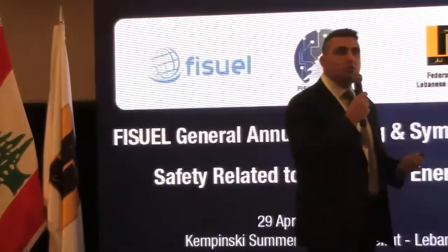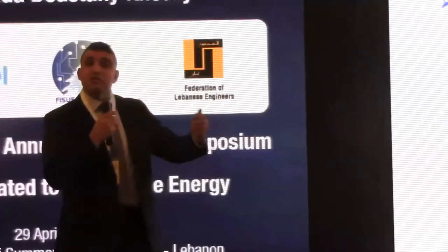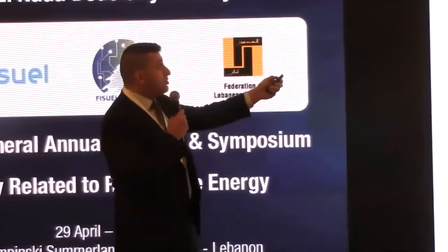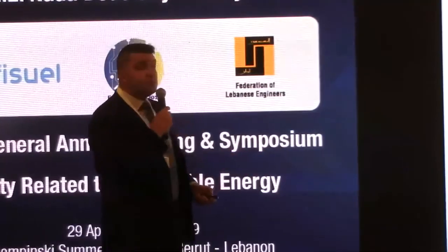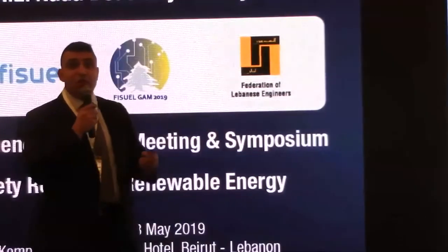Now, after we obtain all this information, we need to decide, as an engineer, on the layout and product. So it's very critical for us to know the soil resistivity, the ground flash density, and the insulation level. The reason is, based on this information, we'll make a decision. Do we place the mast touching the structure or not?